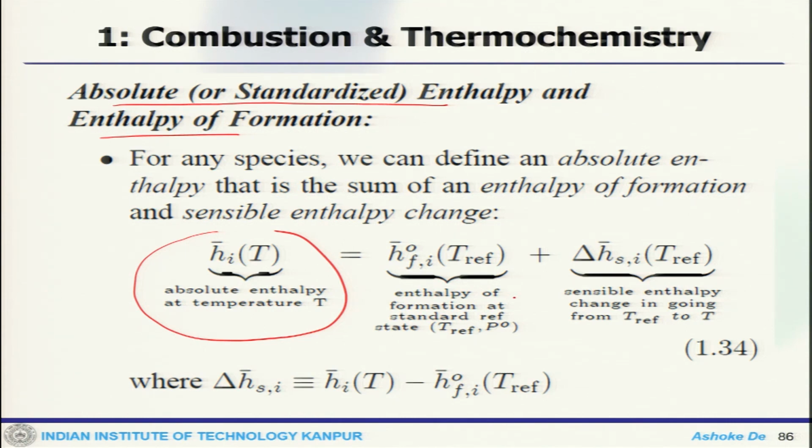One component is the contribution from the enthalpy of formation of a particular species at a reference temperature T reference, and then the sensible enthalpy component, which is nothing but the energy required for the change from T reference to T. So, to go from one state to another, this is the enthalpy change, which at the particular T of concern is the enthalpy at that state minus the enthalpy of formation at the reference state.